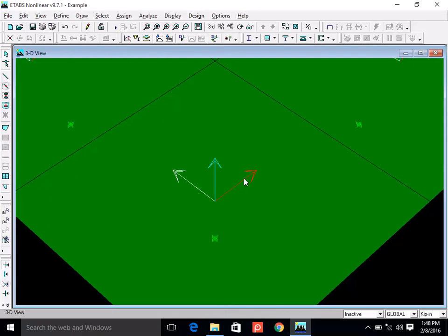But look at this panel, it is 4x supported, but if you get the B over L ratio, that will tell you that this panel is one way, which means that it should bend like this. That's your span. But it doesn't mean that it will not bend in that direction. It will, in part. In manual calculations we ignore that, but when you do finite element analysis, you will have some bending moment in the other direction as well.